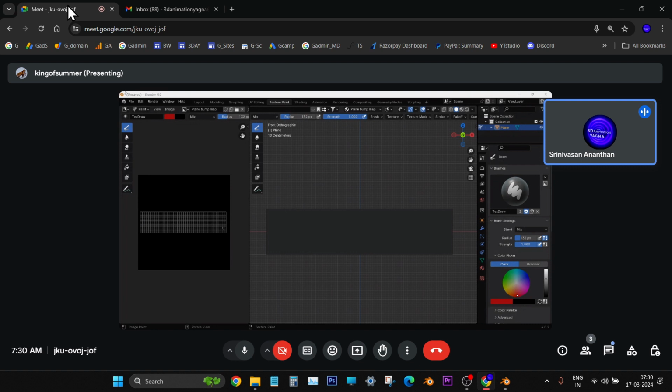Right now you have saved the paintable texture. You are in bump map mode inside the texture paint module. Now we have to bring that paintable peacock texture inside the active tool settings, in the texture column. Go to active tool settings, properties editor, right side, below, go here.